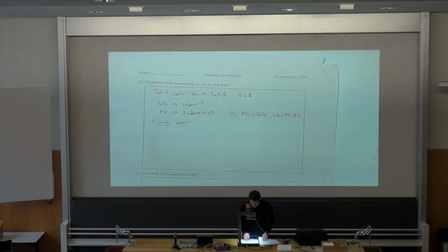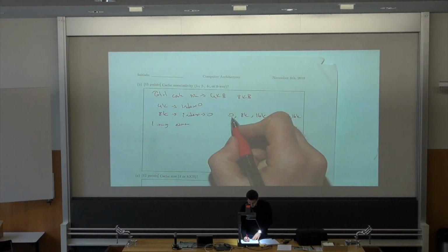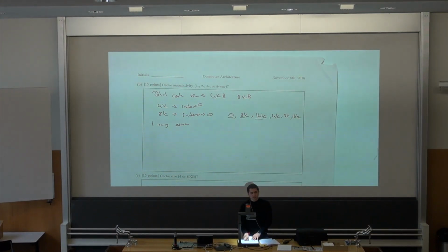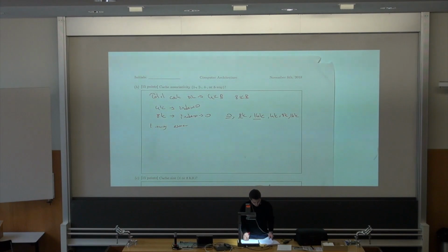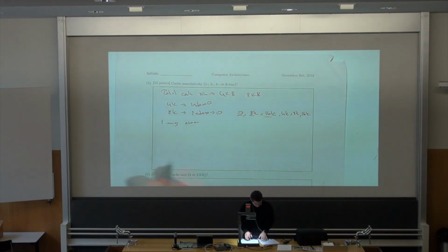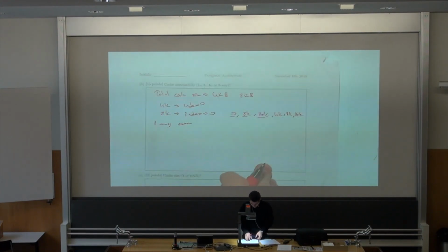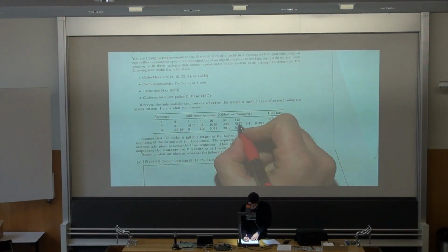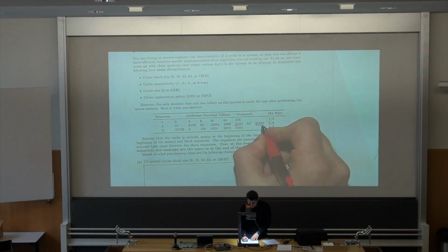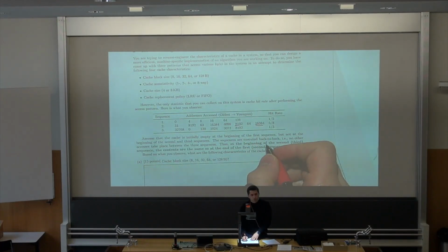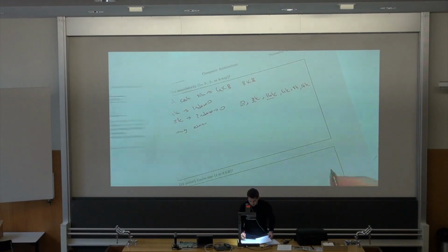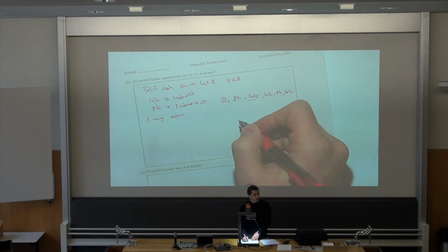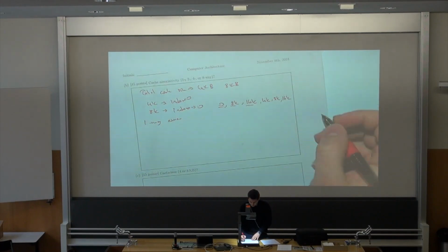If this was one-way associative, then for each access we would be replacing the index block, right? Remember that those accesses need to be hits in order to have 5 hits, right? So it cannot be one-way, because those will be removed if it is one-way, right?